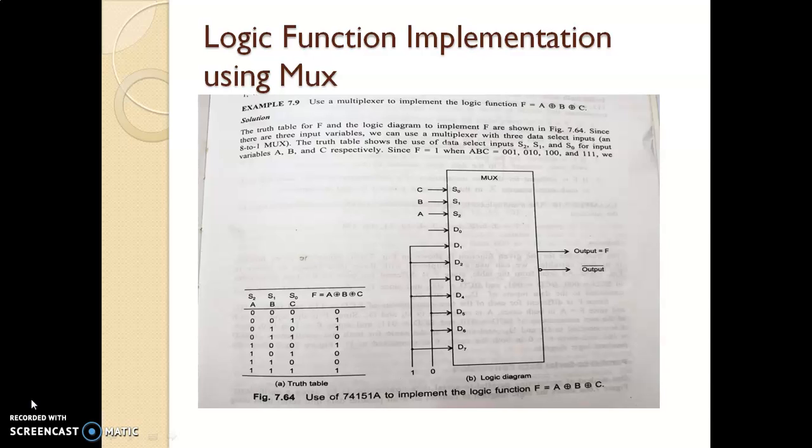So we have written the truth table here with the inputs A, B, C because the variables used here are A, B, C. Since there are three variables, you will have 2 raised to 3, that is 8 input combinations, starting from 0, 0, 0 to 1, 1, 1. Now, what will be the result, that is, what will be A XOR B XOR C for the input 0, 0, 0? That will be written on the right hand side as the output.